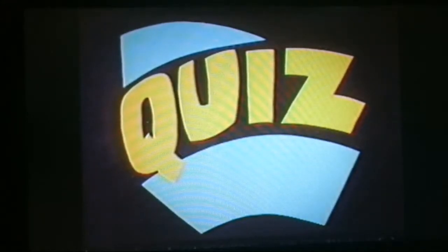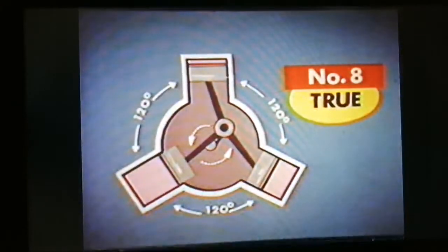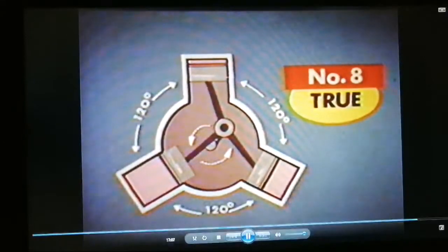Okay, the answer to number 7 is false. The three-phase generator may be slightly heavier, but normally is no larger than a single-phase unit. Number 8 is true. The three-phase generator consists of three separate electrical circuits, or phases, spaced evenly around the 360 degrees of each revolution, so they're 120 degrees apart.